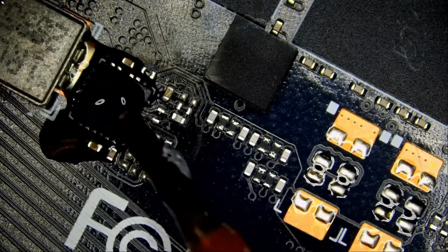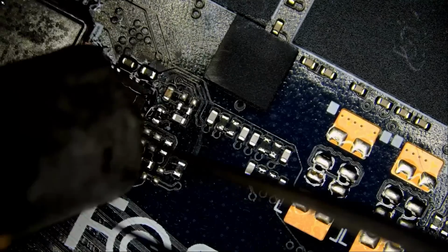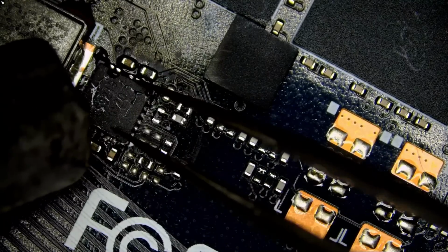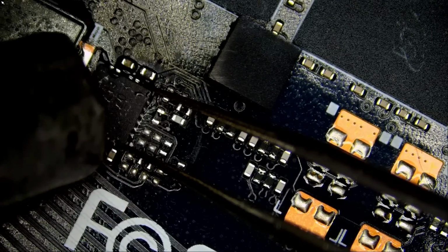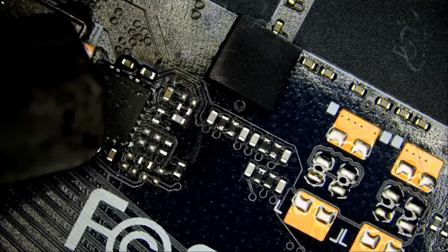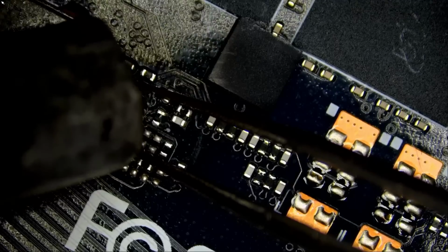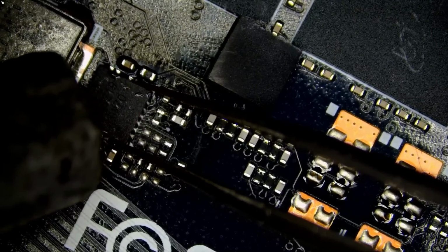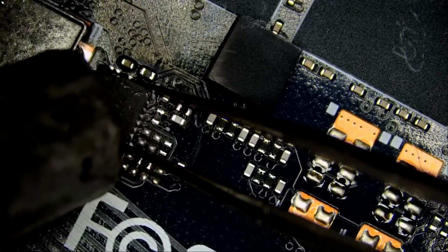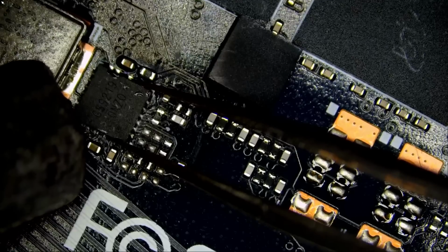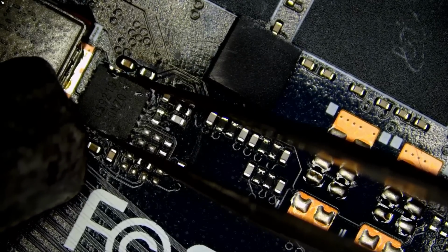Do you need to add flux to desolder a component? No, because I get this question all the time. Sometimes I apply flux when desoldering, and other times I do not. Flux just helps with the flow of solder. Sometimes I do feel that flux helps with desoldering the chip faster, but that's not the purpose of flux. I'm working on a thick board here, so anything that would help remove the component faster, I would use.